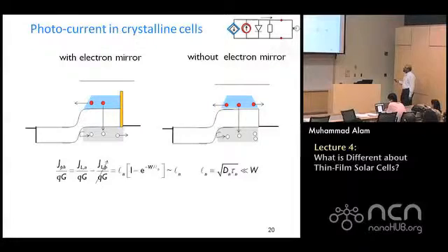Now, you may say, let's take out this potential barrier, but this barrier must be doing me some good, because after all it is sort of reflecting all the carriers, an electron mirror. This should be doing me some good, but actually it doesn't, for the following reason. If you remove it, of course, these electrons will be coming out to the wrong contact. But because the electron number is a little bit less now, the recombination of the holes that are coming out here will also be a little less. And so more holes are going to come out here.